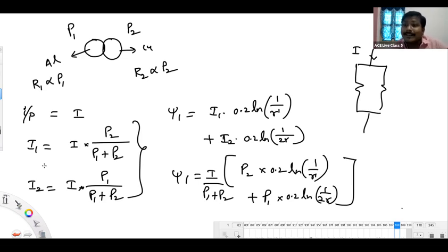But sir, you say the advantage of reactive power is that it is used to create magnetic flux and electric flux. That's an incorrect statement. We just have an inductor, it is drawing current, and it is producing magnetic flux. Then you use the term reactive power. You should not say in reverse that reactive power is needed to create the magnetic flux.